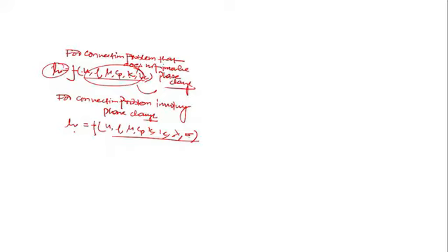And already in fluid mechanics we have seen, when one dependent variable depends on more than one independent variable, then it is very difficult to show the effect of these parameters on the heat transfer coefficient individually. Because if you want to carry out an individual experiment, what should I do? I should keep all parameters constant and change the velocity, and then show how the heat transfer coefficient changes.